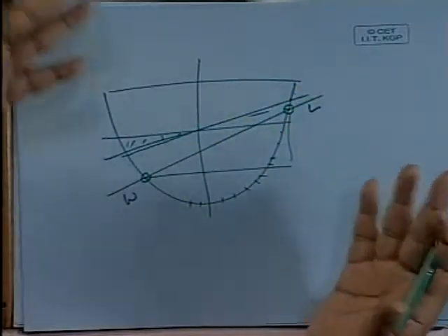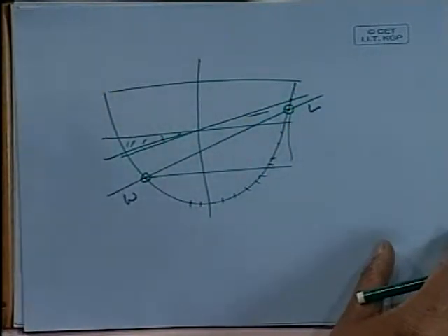So I mentioned two methods. One is a very old integration based method. The other is this newer method based on half breadths given. I think we will not dwell on that any further. My intention is to tell you what is to be calculated, not how it can be done. Since the how part is now enormous, you can use a spreadsheet and go around that and find the number. You can also draw in AutoCAD. There are so many software packages where you can trace this, mark this up, and get the area and the moment. So there is no end to it. Okay.